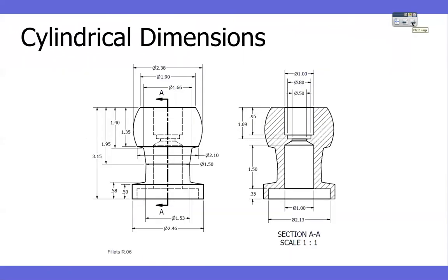So if we have a cylinder, you're going to see the dimensions like this, where you can see the side view of the cylinder, not where you see it round. Usually for holes, we see the holes where they're round, and that's where the dimension goes. For cylinders, you'll usually see it where you're seeing the side of it. If I just tell you a diameter here and then the length, right? This view doesn't tell you anything else. You're not seeing the length. So here you get the length and the diameter. Here all you get is the diameter.